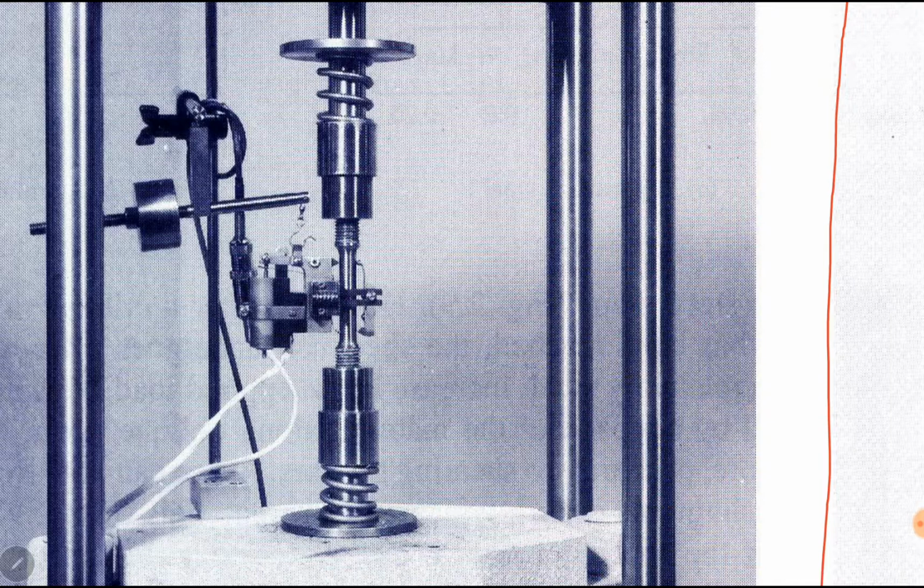FCD is tensile. Now take summation of moments at point D equal to 0. By putting all the values, you can put the moment expression values here, values of force and values of distances, FAB becomes minus 60 kilonewtons. Minus means the assumed direction was not correct. We have assumed FAB to be tensile. If it is not correct, it means FAB is compressive.